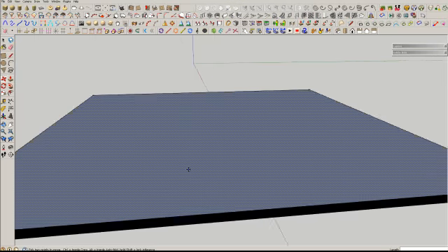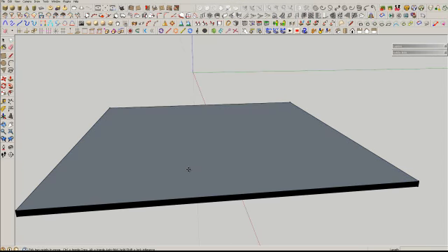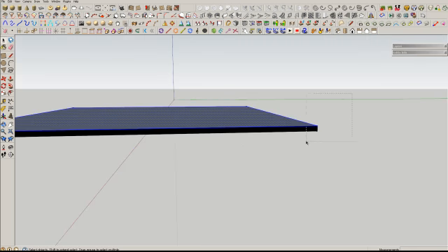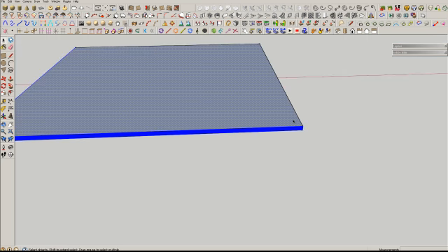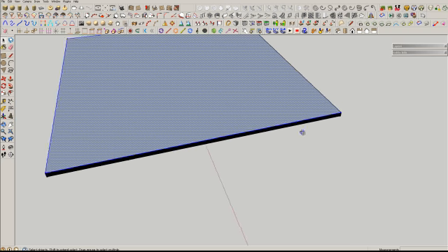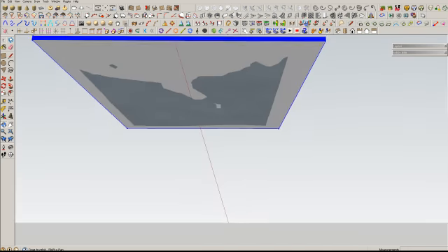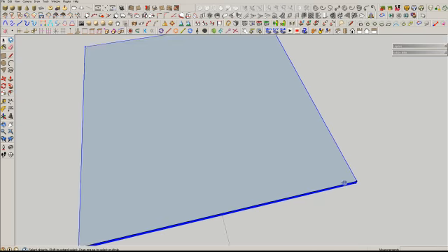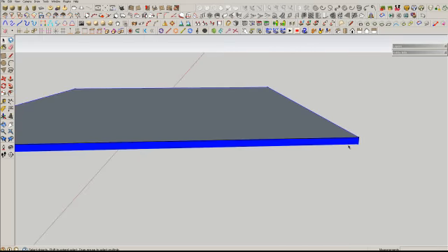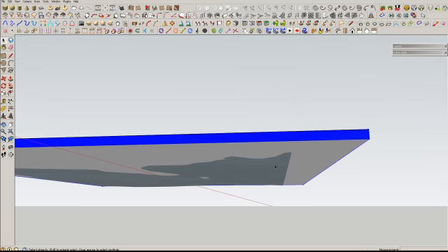Okay, in order to get this again, I'm going to press shift so that you can add in the edges. You need not really add in the edges, but just to make sure that everything is going according to plan, uniformly, you just do that. And you move it slightly down so that it covers the base of the contour surface. Move.